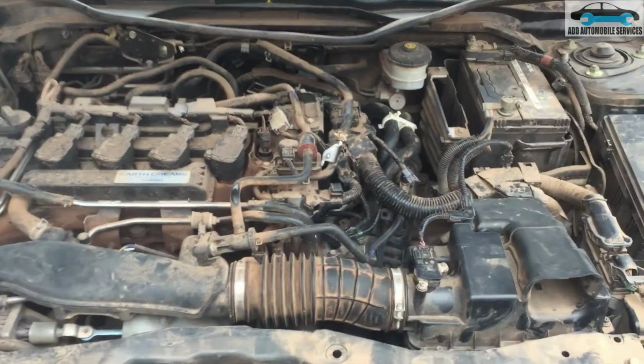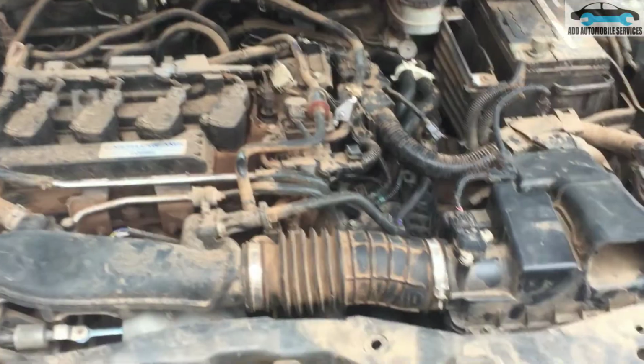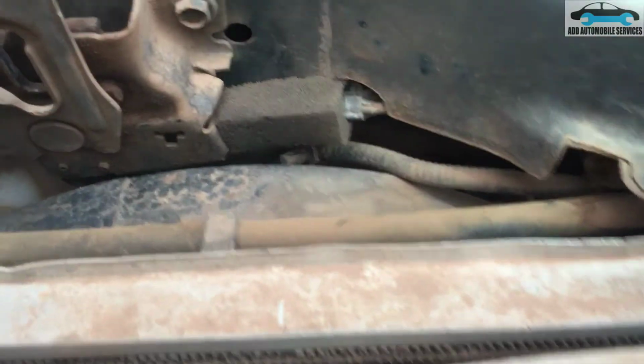When you stand here, you can see the way this hose is looking, and the droplets coming out from there. After several hours of vibration, now I took the thermostat out, and still it was giving me the same issue. So you can see down here, let me give you the light. So you can see down here that there is a water leakage. So this is what is causing the problem.